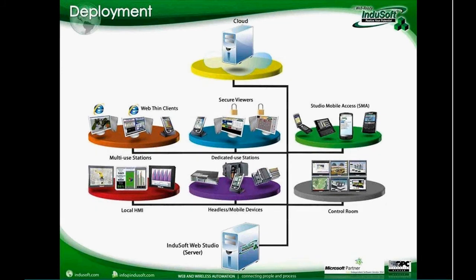InduSoft Mobile Access is the solution for non-Microsoft devices like Androids, iPads, iPhones, and the current solution allows you to visualize and even change tag values in real time, and allows you to visualize and acknowledge alarms also in real time. And we are evolving the solution right now to add additional graphical capabilities, to monitor online trends and history trends, see graphical screens on the device, and visualize even dashboards on a non-Microsoft device using just a web browser.